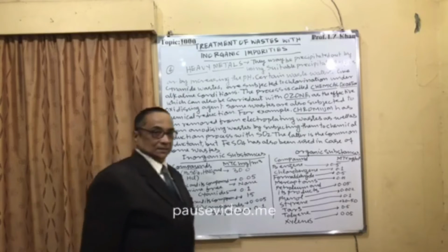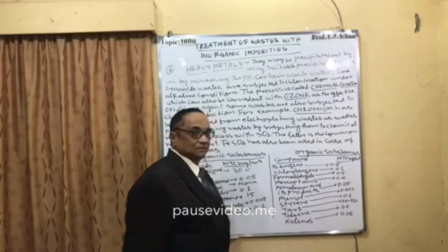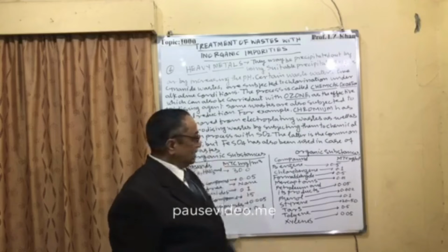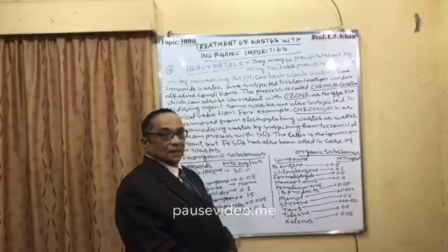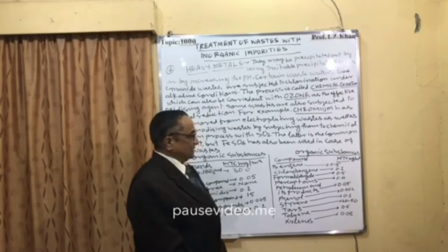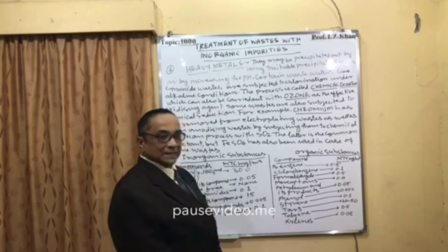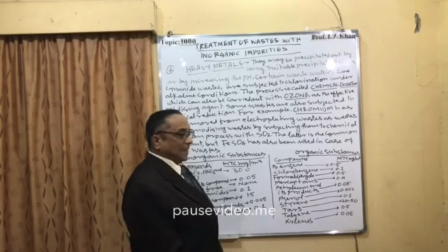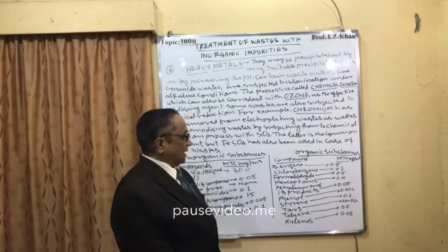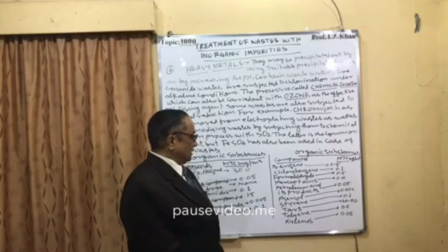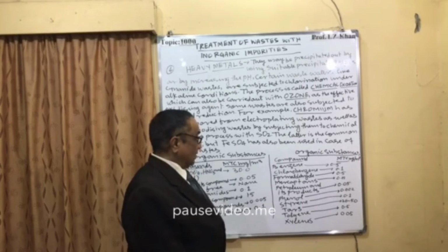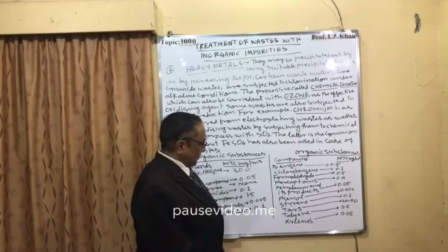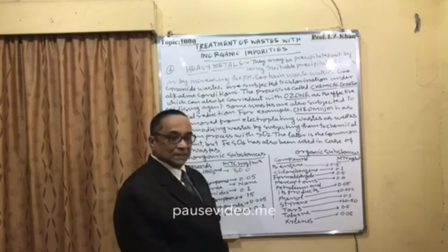The organic substances, as a waste material or industrial effluent, they are compounds and MTC, mg per m³. Benzene is 0.5, chlorobenzene is 0.1, formaldehyde is 0.5, mercaptans are 0.01, then petroleum and its products, that is petrochemicals, are 0.05, and phenol is also very toxic, and phenol is allowed up to 0.002.